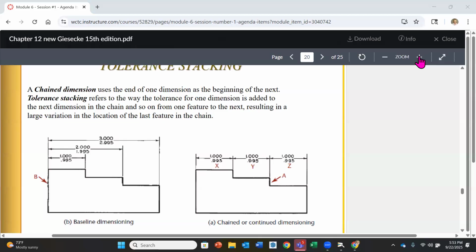Cost of the part. Now, we talked a little bit earlier about tolerance zones and how small tolerance zones are probably going to take a little bit longer or maybe a lot longer, depending, compared to large tolerance zones to create, right? And I think I had kind of said in passing, time is money, right? So the longer it takes me to make something, the more expensive that part is going to be. And if we unnecessarily put tolerances on that are super close, might fit great in the end, right? And it'll go together perfectly all the time. But if we can't make that part economically and there's not a profit left where we can sell our part, and there's that difference in process and that difference in how much it's manufactured, how much we can sell it for, what happens?